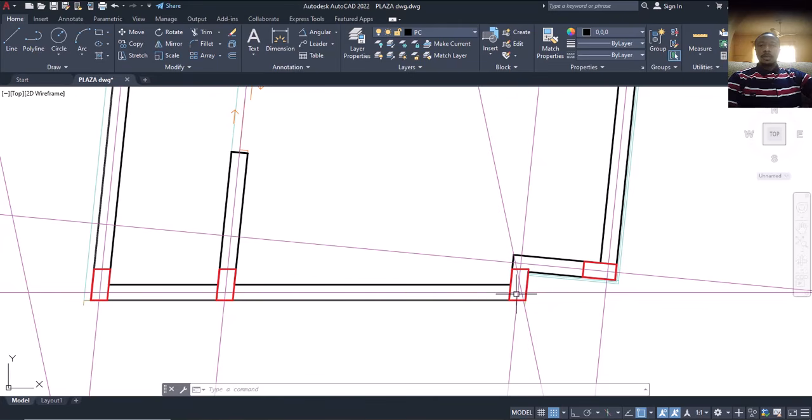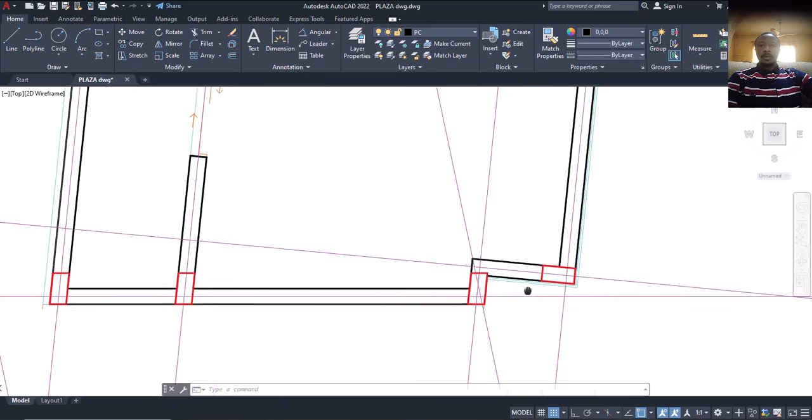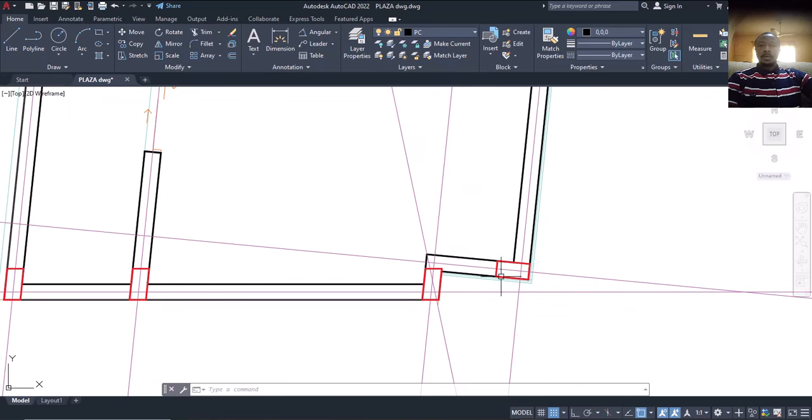If I put this one here and this one is coming, and I'll put another small beam there to connect it, is it going to carry it? Don't forget that the length of this one is even more than this one. And if you look at this one, no drawback beam. Assuming there's a beam coming like this perfectly, I only put one column here, then this one will serve as a cantilever, and this one will not go and rest on it. Do you see it now?